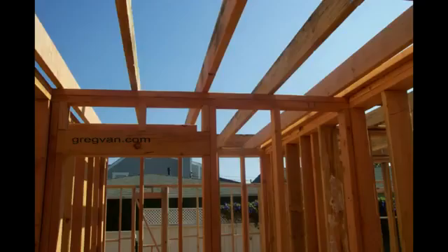Now here's an example of what a wall might look like that would be non-supporting or non-structural. And this would be whenever you would have the end of the ceiling joists connecting to another part of the building. It would either be connecting to a beam that would be supporting the weight at one end, or it would be sitting on top of a wall. So it's got to be supported somehow. And if you run across something like this, where you have a wall that's in the center, there's a good chance that that's not going to be a structural wall.